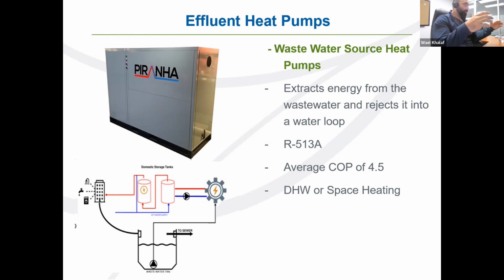The Piranha isn't a very tall unit, it's probably about 5 feet tall. You take the top off the stainless steel evaporator, and at that point it'll be completely empty. If you have biofilms forming on the inside, you grab fresh water, soap, and a scrub, and it's open to the atmosphere at that point. You just clean it up and flush it down, and that's it.